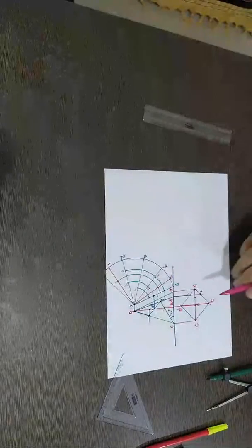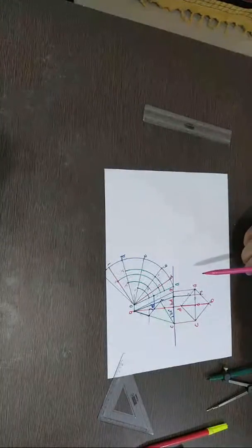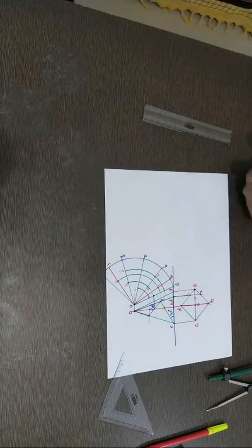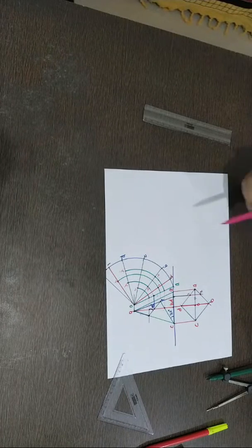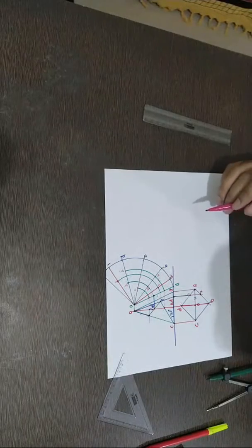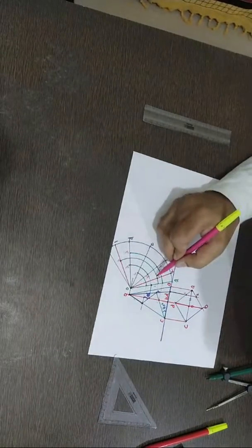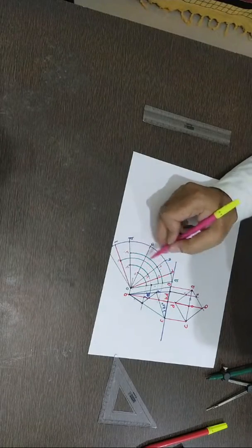If I use notation everywhere, it will make it very difficult to understand. But if you use the logic concept, it's very simple. It's just the corresponding intersection transferred onto the corresponding generator or slant edge. That's it. So I got how many points? 2, B, C, D, 1, D dash and B dash.